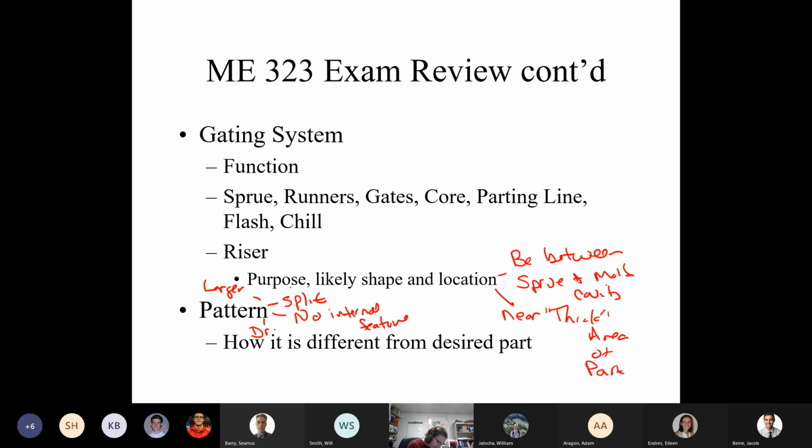It may have draft, and we also may have some V over A concerns. So like the example I showed you where a change was made to increase the efficiency, so to speak, or decrease the amount of machining on the pattern, and then it actually influenced the V over A to a negative extent.